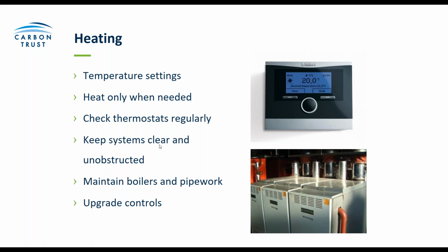Checking thermostats regularly as well, so just making sure that any thermostats that are accessible aren't being turned up by the occupants of the rooms. One of the common misconceptions that we often come up against is that turning the thermostat up as high as it goes makes the room warmer quicker, when in actual fact the only real effect that has is that it heats the room up at the same rate that it normally would. You just then end up with a bit of overheating at the end of that.